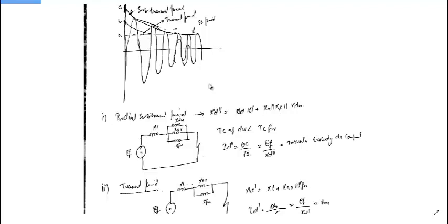What I mean to say is that our equivalent circuit of the synchronous machine in the initial period will be like this. It will be the leakage reactance in series with the parallel combination of this damper windings, this armature reaction, and field winding reactance. So these three will be in parallel because this damper winding will also carry the current, armature reactance will also carry the current, this field winding reactance will also carry the current.